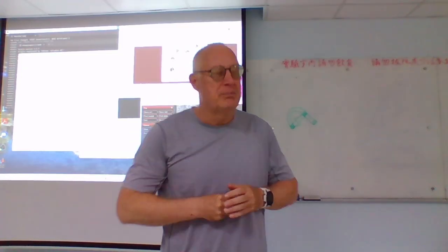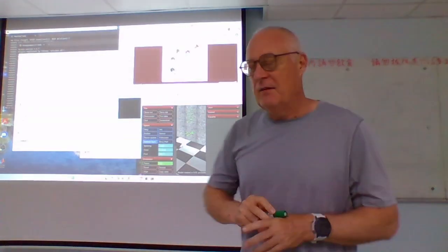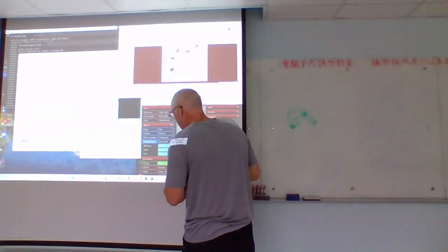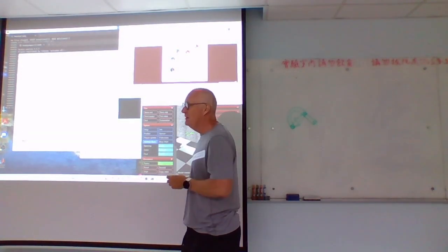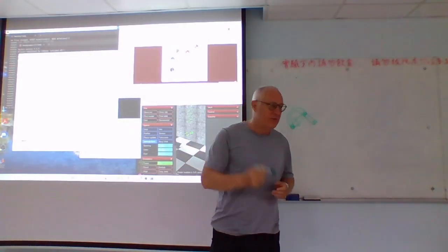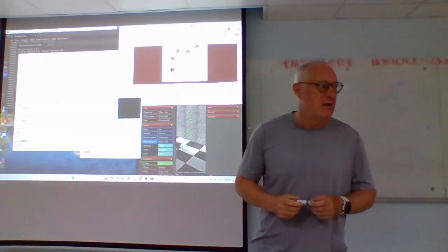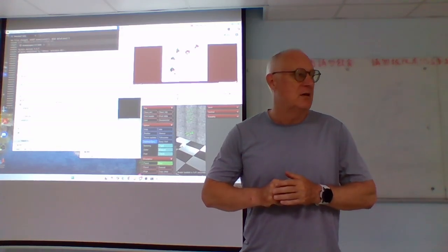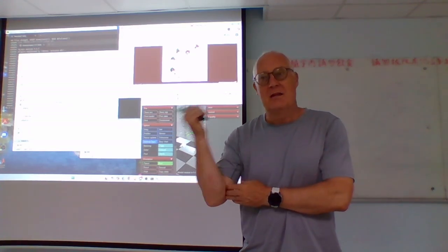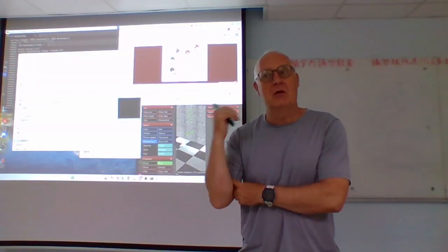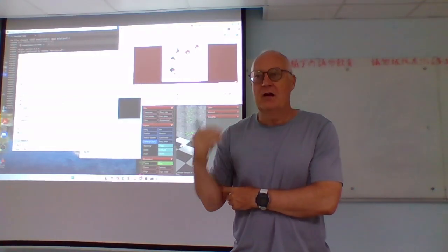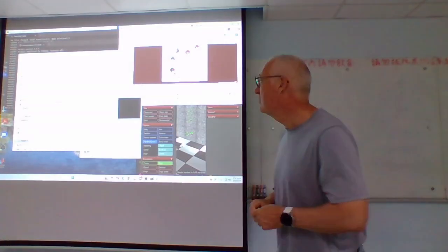So to simplify things, one of the conventions is that the z-axis is the axis of actuation for a joint, and for a revolute joint, that means the axis that we rotate around, so we always rotate around the z-axis from x to y in the positive direction.